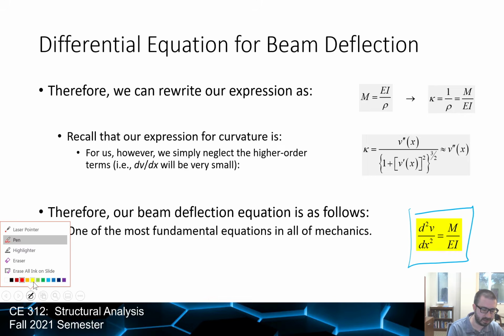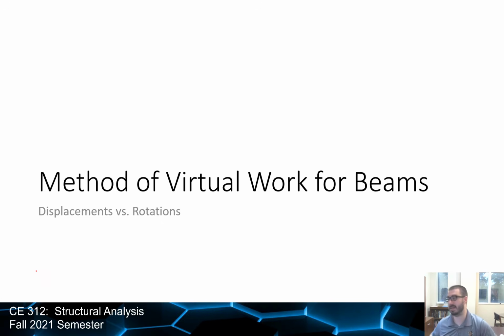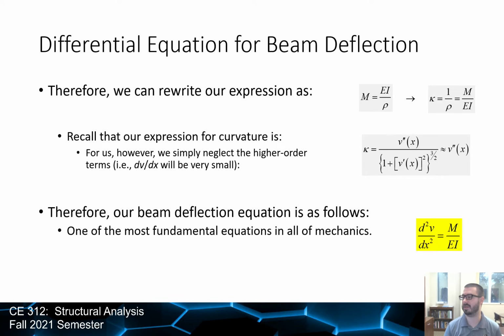One of the things I'll mention is that we're using virtual work in this course to compute deflections. There are other ways to compute the deformations in beams, and your book is littered with other approaches. For example, there are geometric methods, which are all about trying to come up with solutions to this differential equation. Some of them directly solve the differential equation. We call that direct integration. Some of them use the geometry of the solution, for example the conjugate beam method, in order to assess the deflection at a given point.